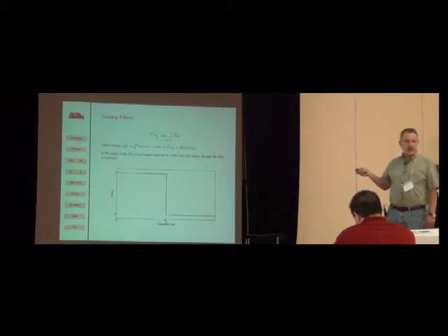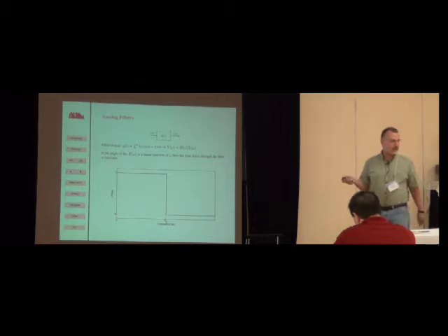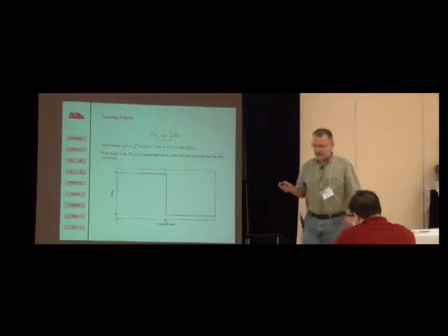So you look at the magnitude of the transfer function, and here is just what you might wish to achieve. This is an ideal low-pass filter, so it's 1 over some pass band up to some omega p, the pass band frequency, and then it cuts off anything at a higher frequency entirely to 0. Of course, a filter like this can't be achieved, but often you'd like to achieve this sort of filter, at least do the best you can.